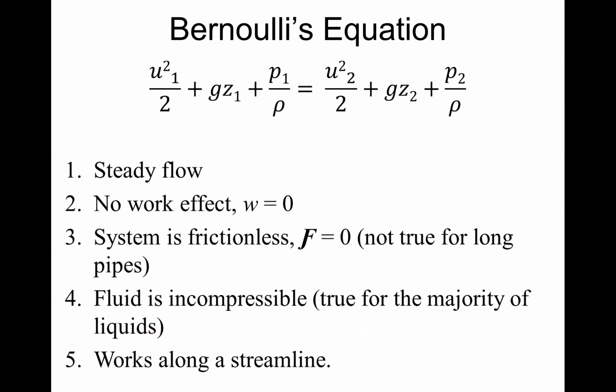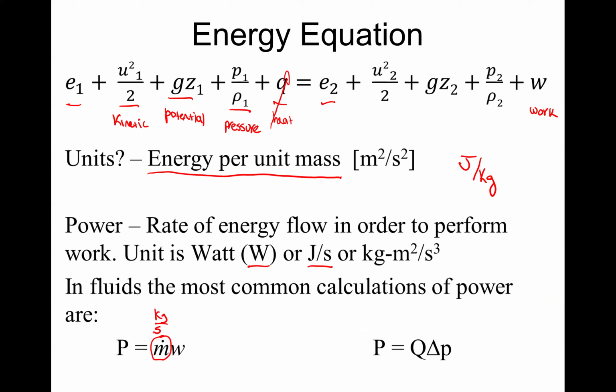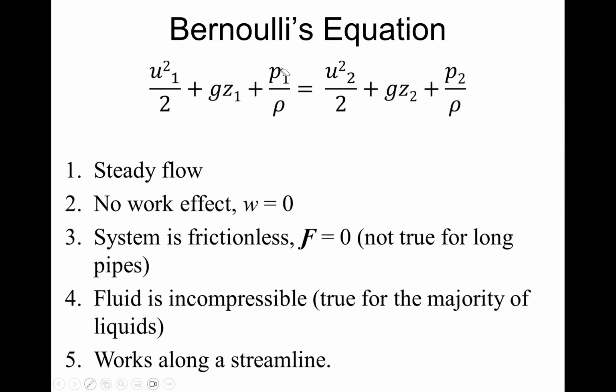Now, I take that equation, which is pretty big, and I make some assumptions. First, there is no pump, so the work is gone. Second, there is no heat, as we said. And third, there is no internal energy to be considered. When we do this, we are assuming a few things. No work effect, which I explained. Steady flow, because we are moving along a streamline.